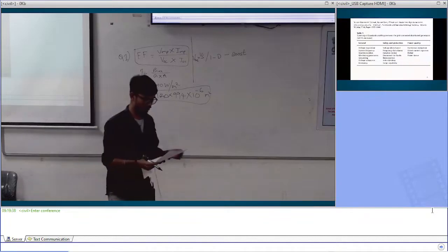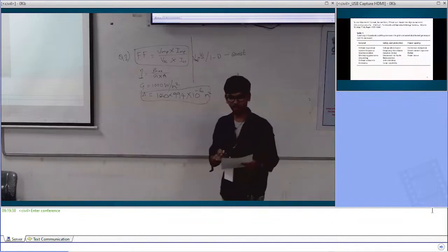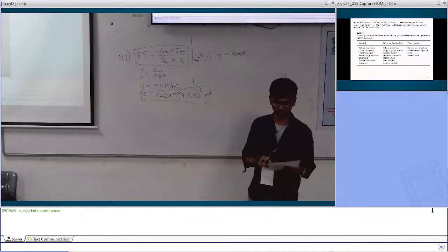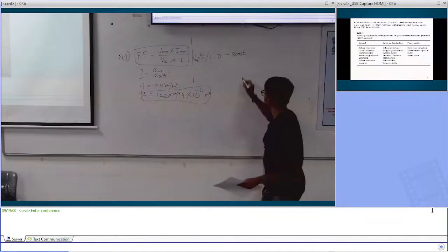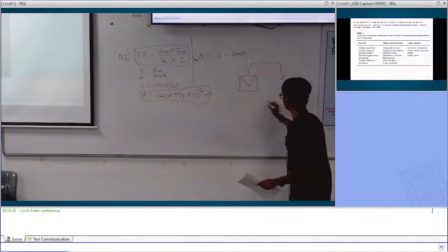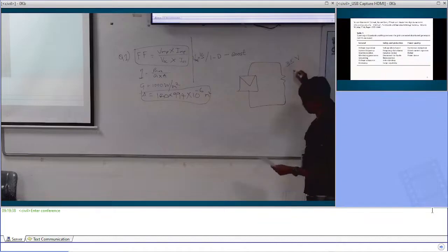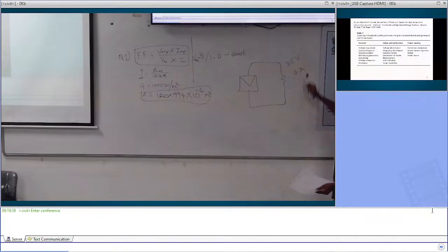The next part of the question, we have calculated the operating point with 35 as voltage and 7 as current in the normal condition, that is, PV is directly connected to a resistive load. At this condition, we have operating point as 35 volts and 7 amps of current. With this we can find the value of R. V equal to IR, so we can find the value of R.